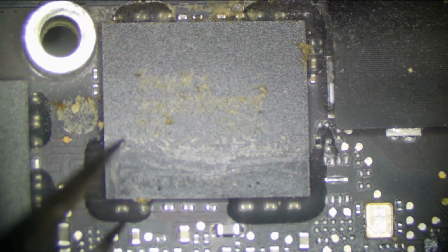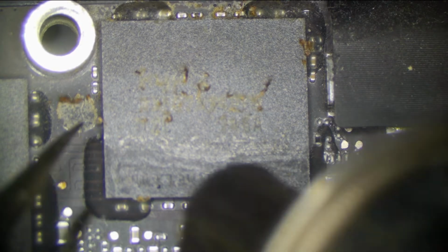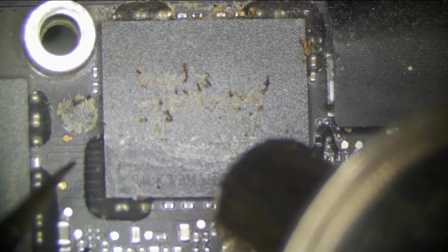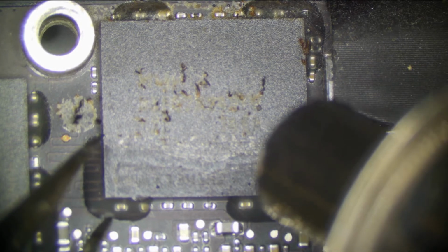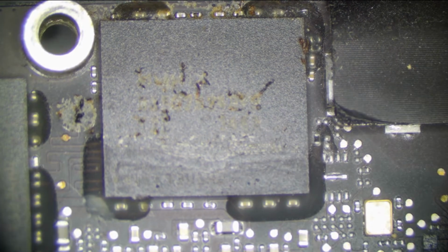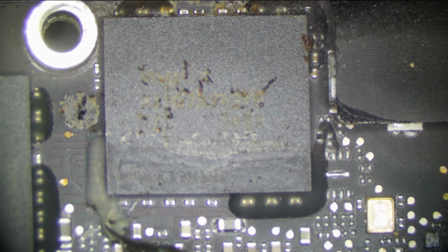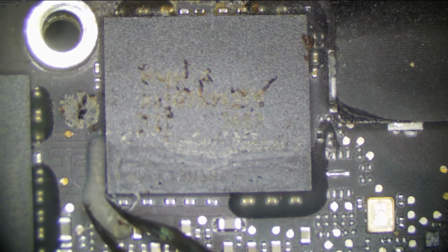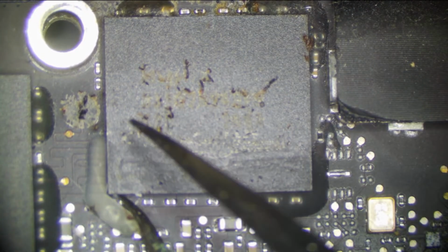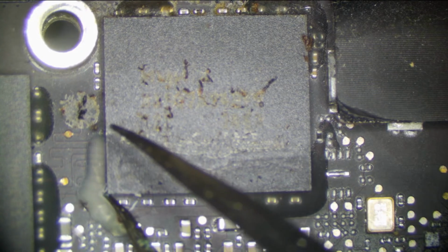So I'm going to heat this from far away just to loosen the edge bonding a little bit. I don't want to heat it up too much because then the edge bonding is going to get brittle, and I don't want that. You don't want to leave any edge bonding under it. If you don't remove it completely and you reflow the chip completely, then you could have some serious issues. So make sure the edge bonding is completely gone. And if I can't get it, I won't reflow it completely either. But I think I'm fine.